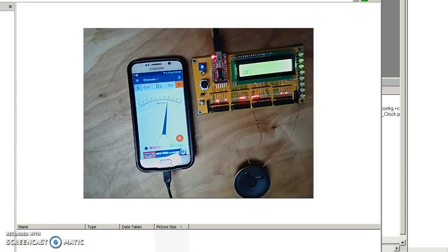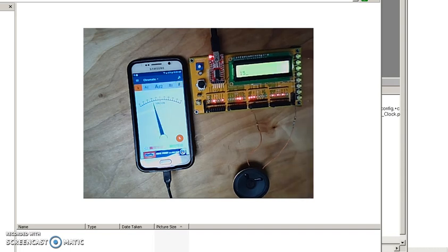And if you look at the resulting code, every 1 second precisely, the count's increasing. So there I've got a binary clock measuring time to 1 millisecond, even though the LCD routine takes about 14 milliseconds to be called. That's one application.